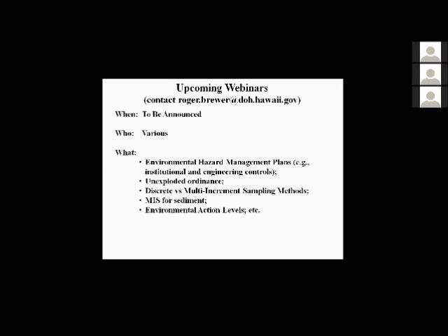Okay, thanks, Harry. Hey, Harry, this is Roger. I have one more question for you. Let's say I want to determine the mean concentration of a VOC within the middle 1/3 of a building slab. Can you install multiple passive samplers and then combine them in the analysis, so I just get one analysis and just one number? I'm not really interested in the variability. I just want the mean.